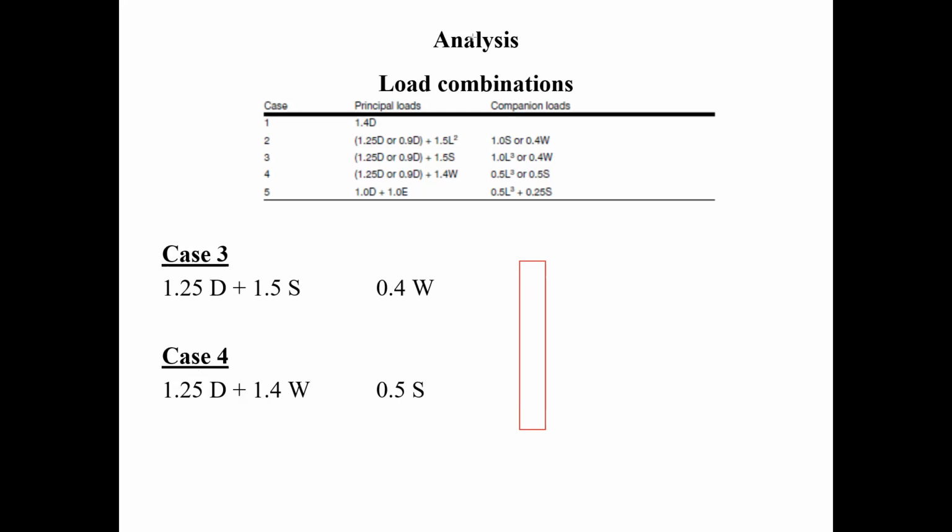Your equations for pressure. Factored, right? Pardon? It shouldn't be factored. Like I'm going to take the value of the W without any. Well, the W that we calculated right now, we said it was 0.94. I'm not saying that that's right or that's wrong, but that's the value that we're using. Okay, 0.94 kPa. That's our wind load right now, right? For strength, for ultimate limit states. What would it be for serviceability limit states? It's going to be the same, isn't it?